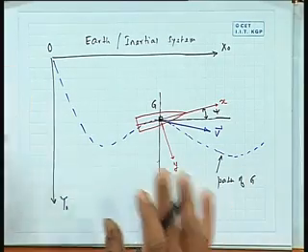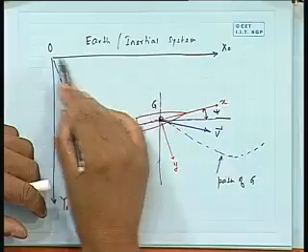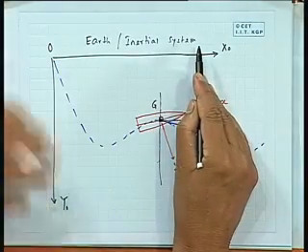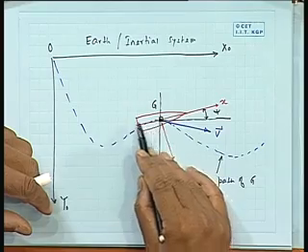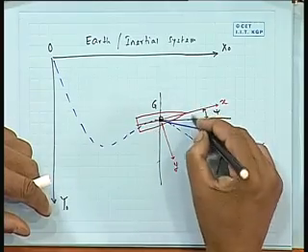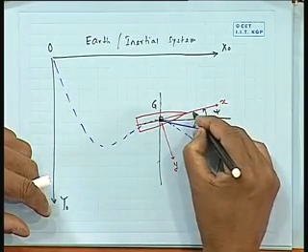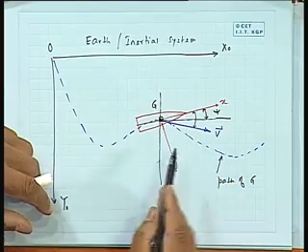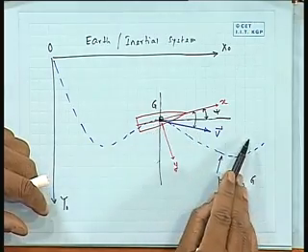Actually, normally in navigation you talk in terms of heading 180 etc., where you would have decided that with respect to another frame of reference, perhaps with an earth system, like longitude, latitude etc., but that is different. You have a reference line here fixed on the earth, on the shore, with respect to which the ship has a heading angle. This angle is what is called the drift angle, because the ship is moving this side.